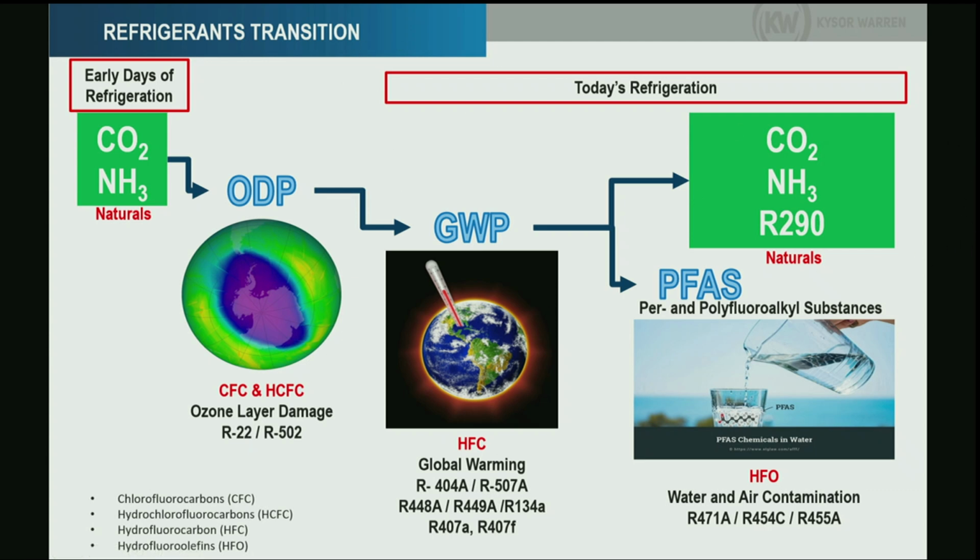And those are great refrigerants. What happens, at least with ammonia, is that ammonia is toxic and mildly flammable. That is the main reason why ammonia is not being used in supermarkets. However, ammonia is highly used in industrial applications when they have bigger loads because ammonia is the best refrigerant that we can have. It has a lot of cooling capacity, and it can remove huge heat loads from the space with a small amount of ammonia.